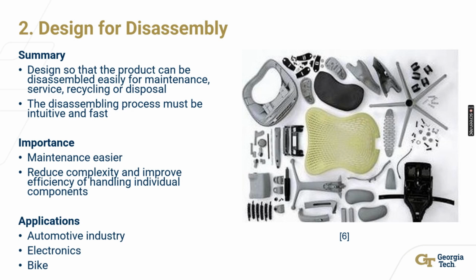The second topic is design for disassembly, or DFD. It makes the design so that the product can be disassembled easily for maintenance, service, recycling, or disposal. The disassembling process must be intuitive and fast. Some importances are that maintenance is easier and it reduces the complexity and improves efficiency of handling individual components.